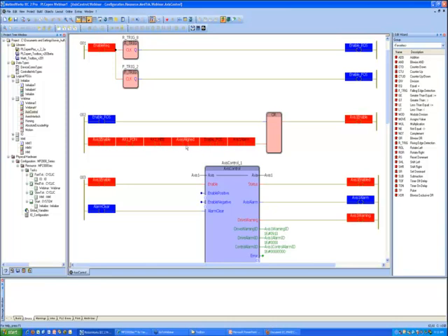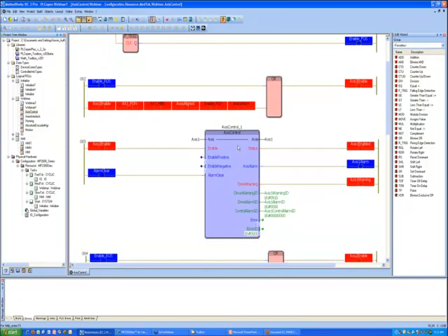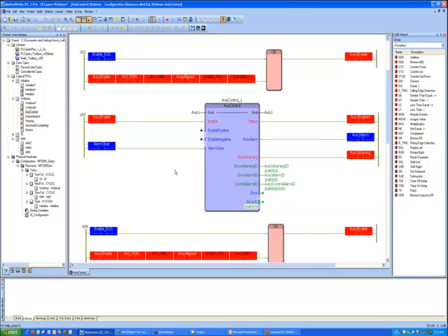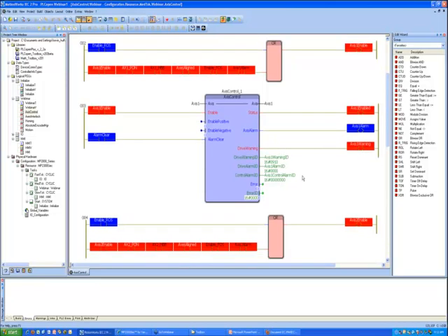But as you can see, I have a 2-axis demo kit system, and my axis 1 has a warning currently. And the warning, this is part of the feature of the axis control function block, is we break out the difference between whether it's a controller side alarm or a drive side alarm. And so it becomes clear if you look at these output values in hex, which is the same display format on the front of the amplifier, that right now I have an A91 warning, which is displayed right here under the drive warning ID.